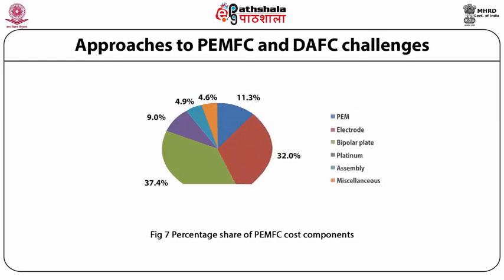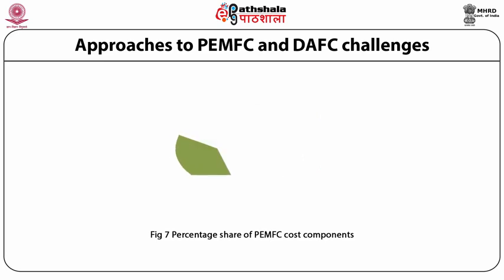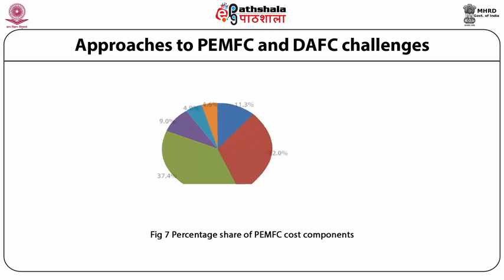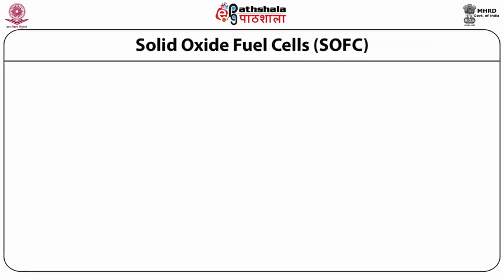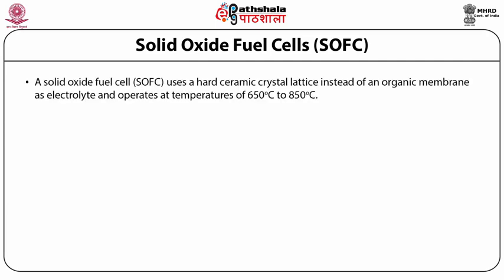It would be difficult for fuel cell technology to become competitive with other energy conversion technologies unless the overall materials cost is reduced significantly. Solid oxide fuel cells, or SOFCs. A SOFC uses a hard ceramic crystal lattice instead of an organic membrane as electrolyte and operates at temperatures of 650 degrees Celsius to 850 degrees Celsius.